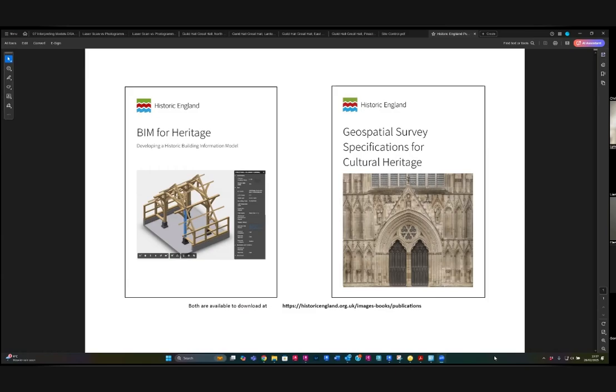You were talking about the tolerances on that. Yeah. If you have a laser scanner and the beam is 1 mil wide at 10 meters, at 100 meters, I can't think off the top of my head, but say it could be 10 mil. So the data at a further distance on a laser scanner isn't going to be as good as at close range.